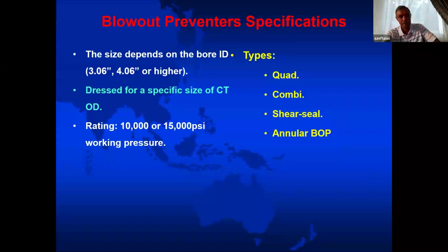Should we rig up and pressure test? If it passes the test, continue the job, or wait and bring a third party. Let us test it to 1.5 as per the API, 1.5 times the working pressure. If it passes, we recertify it and then we use it, or some other answers you might have. I'll give you a minute. I need to see your answers.